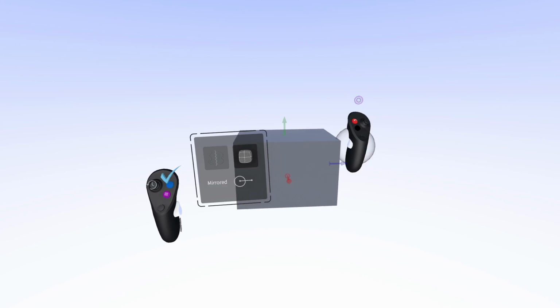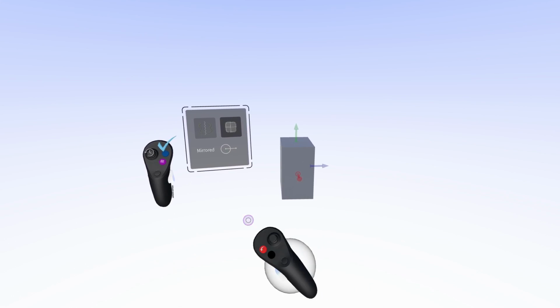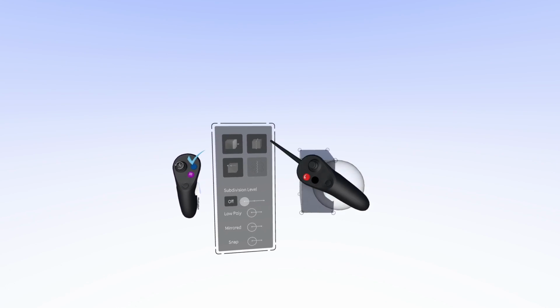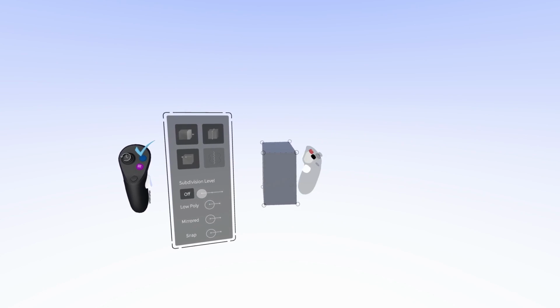Then grab the object with the grab sphere and put it into edit mode. You can adjust the shape with the arrow sliders, and then on the menu, press convert to sub D. Now you notice the menu changes, and when you highlight the object, you can grab faces, vertices, and edit points.